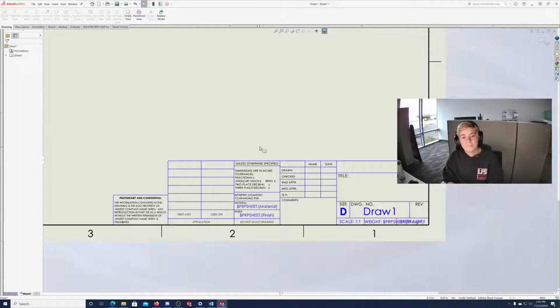If it's off by 10/1000ths of an inch, maybe that part isn't going to fit where it's supposed to. But if it's only off by 3/1000ths, it'll be fine. So they're going to say it can't be off by more than that. And then we know it'll work, but we know it's not going to be exactly 1 inch. Depending on how precise your measuring tools are, you're always going to be able to find a little bit of difference between the real life part and the measurements it's supposed to have on the drawing.